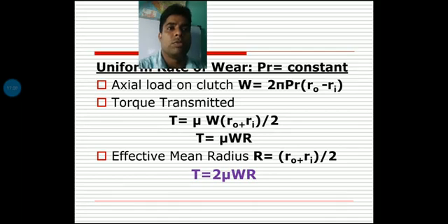If you do not clearly describe which theory is applicable for that particular problem, you cannot solve the problem with proper guidelines. But if a problem does not specify the theory, you have to consider both theories, uniform pressure theory and uniform wear theory.